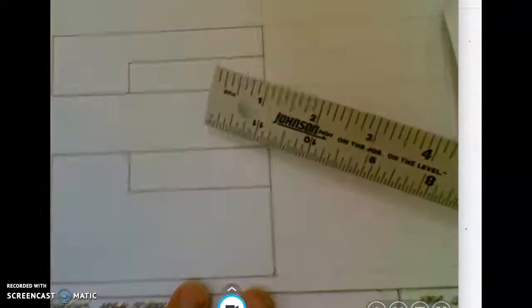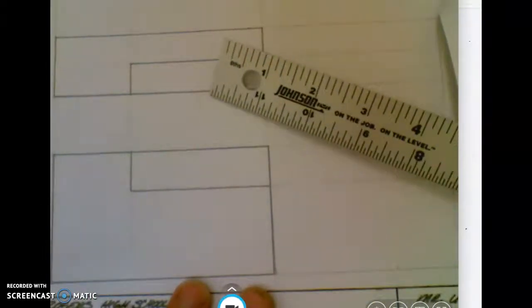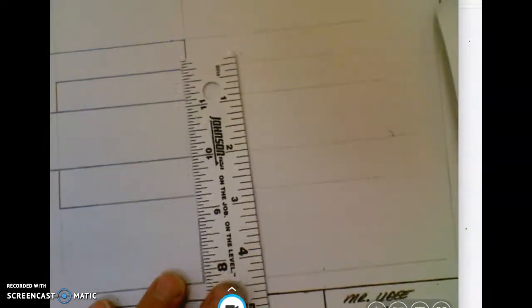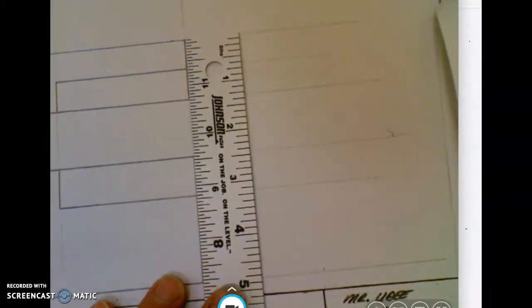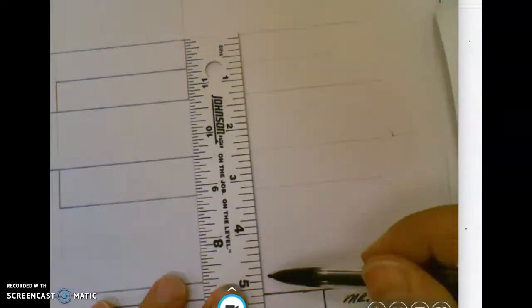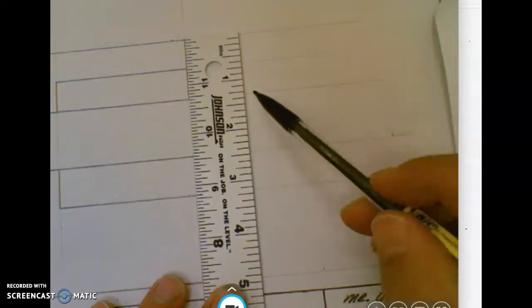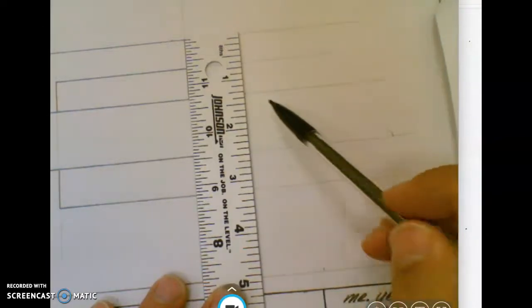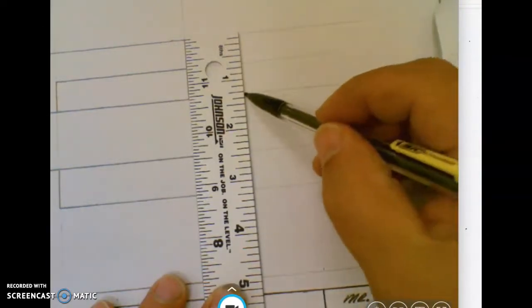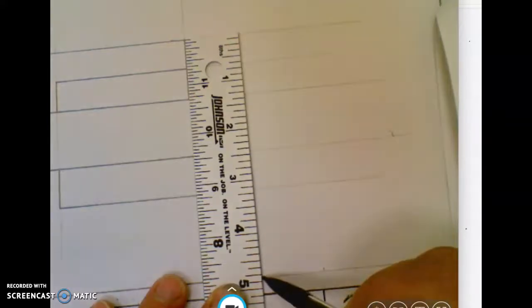So, the first thing I need to do now, again, as I did with these two views here, is give that approximate 1-inch spacing in between my views. So I'm going to take my ruler, line it off the front and the top, and I'm going to start down here at the very bottom of where that side view is going to go, and I'm going to stop it at that first edge of my top view, and you'll see why here shortly. So just a very light construction line to show my spacing. So now I have approximately 1 inch in between.